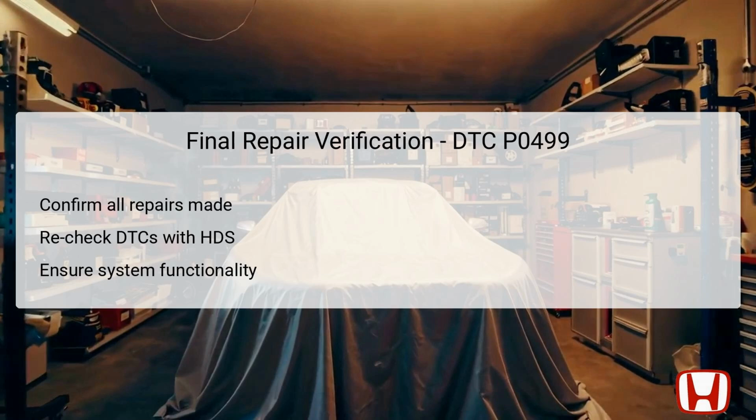This verification process serves to confirm that the repair has resulted in the EVAP canister vent shut valve functioning correctly and, subsequently, ensures that the vehicle is operating within prescribed emission standards. System functionality checks are vital to ascertain that no new error codes have appeared, affirming that the vehicle is back to normal operating conditions.